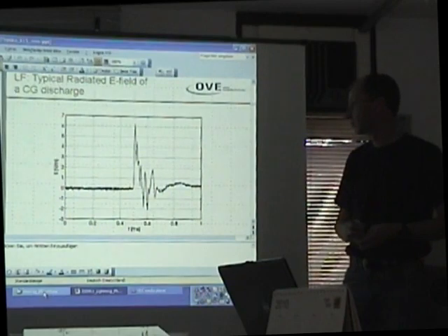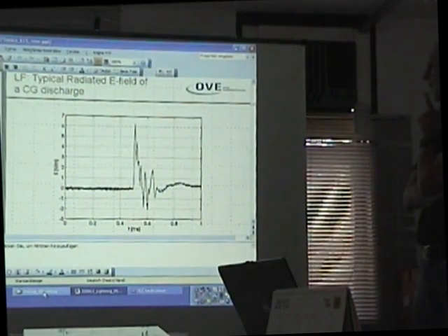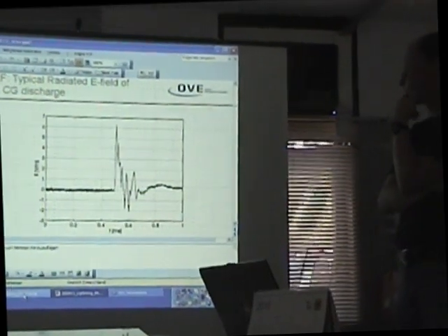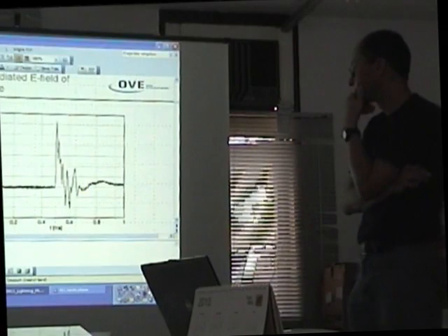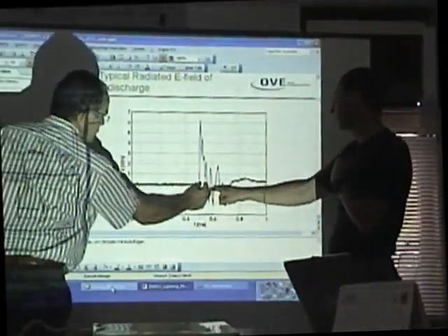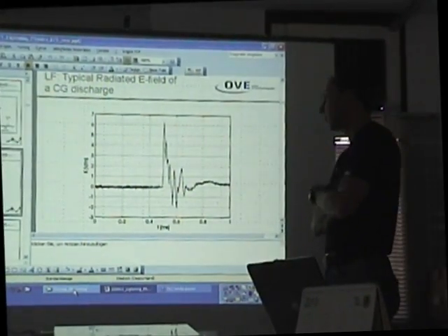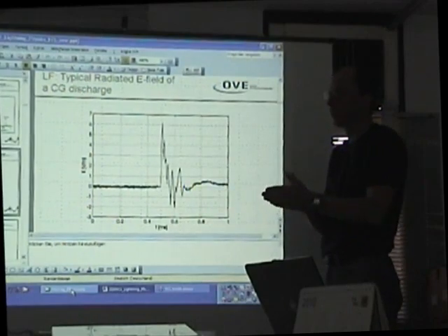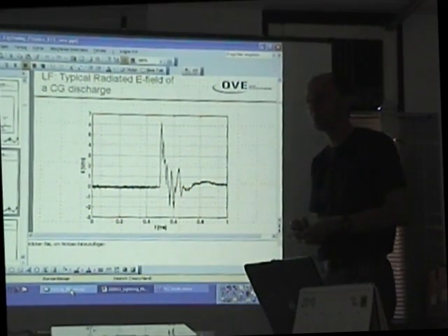The peak to zero measurement is done when it first crosses the zero in the recovery part. It can vary a lot because sometimes there are nearly two crosses, three crosses. This one nearly crosses. It almost crosses. Could be this or this. And I think the zero crossing should be only bigger than 8 microseconds. Everything is bigger than 8 microseconds.